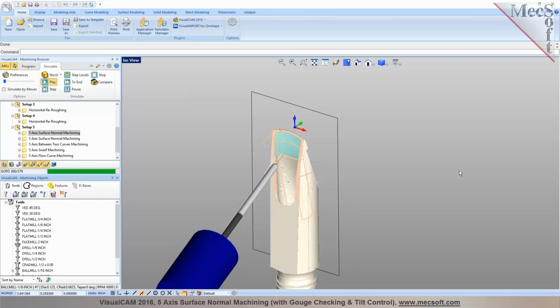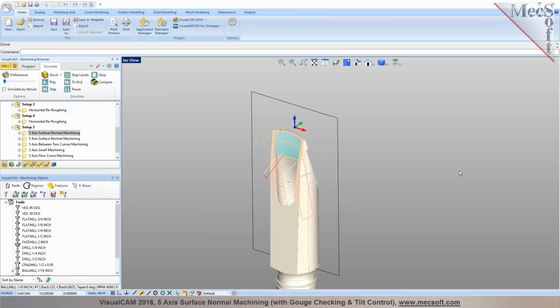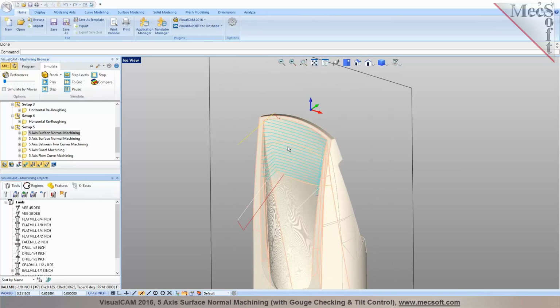Currently, when we put in rotary axis limits, it tries to identify a solution within the limits. If it can, then when you post it, it says it's violating the limit. So you may have to reprogram those areas, or you may have to split the surface to avoid those surfaces from being machined. Because in simultaneous 5-axis, everything is driven based on the surface normal.